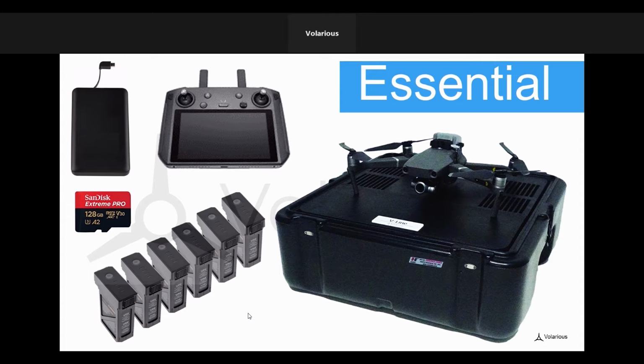Avoid using the RC standard controller, and we recommend using the RC smart controller instead because you will be able to charge concurrently with the portable charger when you're doing long operation that extends beyond the battery life of approximately 2 to 2.5 hours.